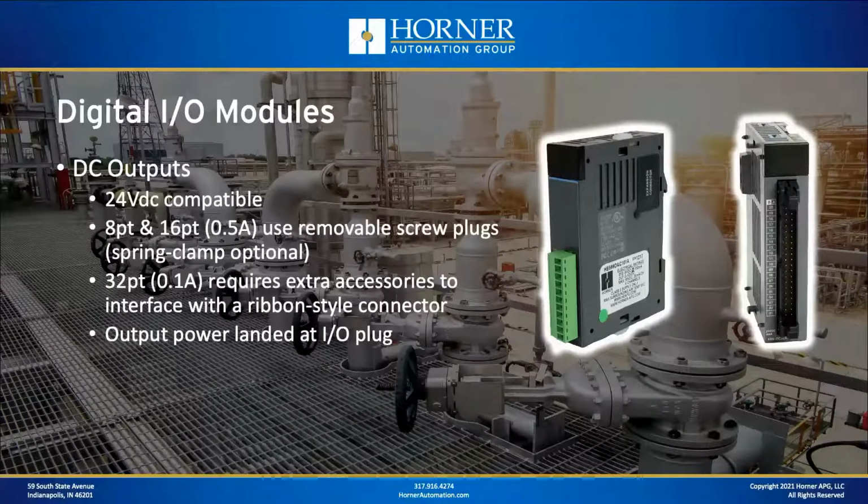Moving to DC outputs, also 24 volt compatible, also available in 8 and 16-point densities that include IO plugs, also available with a 32-point higher density 1/10 amp output compatible module. And again, it's got that high density connector. If you're going to use the 32-point module, you're going to need to buy extra accessories. Also, the output power to drive the outputs, which is true for really any PLC output module and is also true for SmartRail, needs to be landed on the IO plug to power the IO devices.